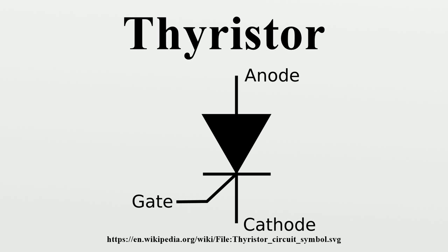Attempting to positively bias the anode within this time causes the thyristor to be self-triggered by the remaining charge carriers that have not yet recombined. For applications with frequencies higher than the domestic AC mains supply, thyristors with lower values of TQ are required.